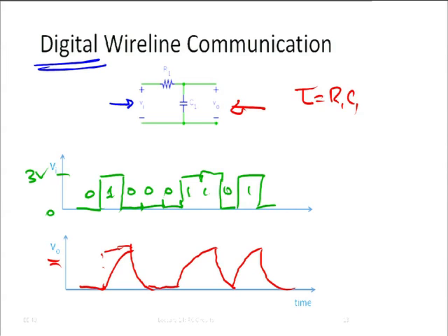One other thing: anybody now has a system with HDMI. The dorms are not that big, but if you separate your projector and the source, the DVD or so, by far, you need a long HDMI cable. Can you have a 100 feet HDMI cable? Not going to work. We know why now, right? This tau gets really, really long, and the voltage simply doesn't reach the right value, and that's why it stops working when you make it too long.